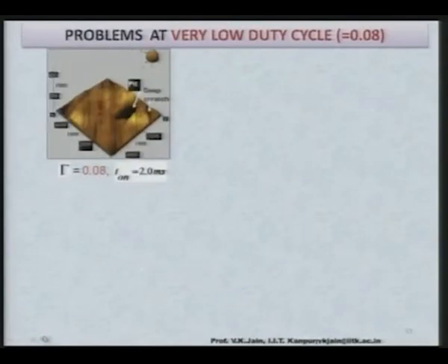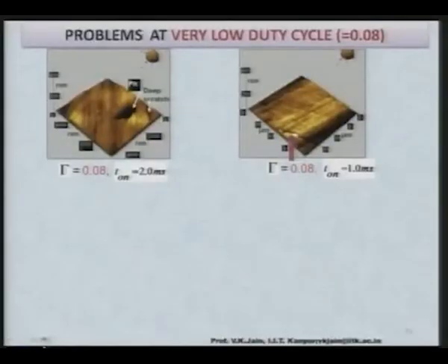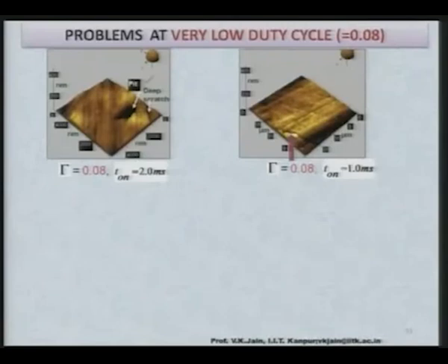But as I mentioned a minute back, the force is very large in case of very low duty cycle, and due to the very large normal force, the penetration of the abrasive particle is very deep, and as a result it may sometimes result in defects in the finished surface. As you can clearly see here, a pit has been formed, and this pit has been formed because of very deep penetration of the abrasive particle due to very large normal force acting on the workpiece through the abrasive particles. So, these kinds of defects are not acceptable on the finished component.